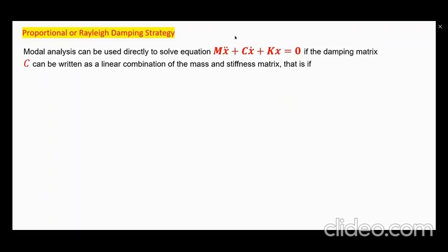And that kind of brings us to a full stop, because the whole idea behind what we did for the last week or 2 weeks or so was that we decouple the equations. If we cannot diagonalize this with the same transformation which diagonalizes M and K, well, we can't proceed any further. The whole idea is to decouple these. So if these are diagonalized through M tilde and K tilde, this better be diagonal too, so that these equations are decoupled.